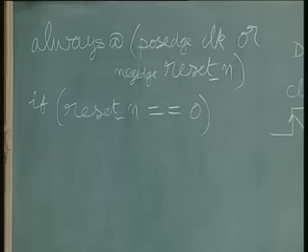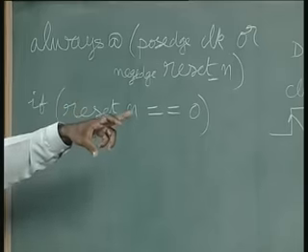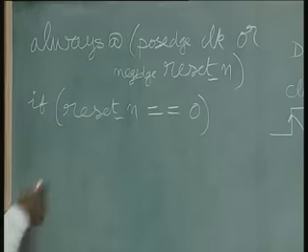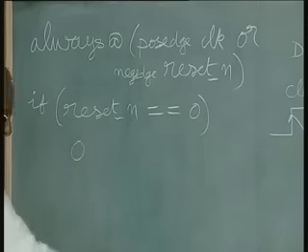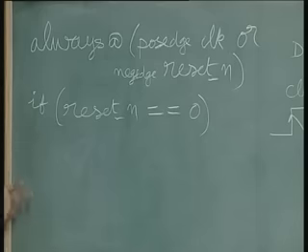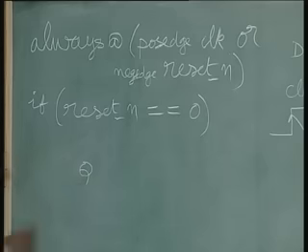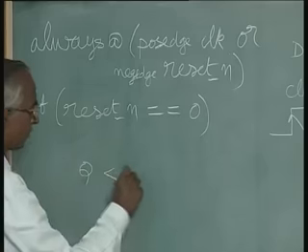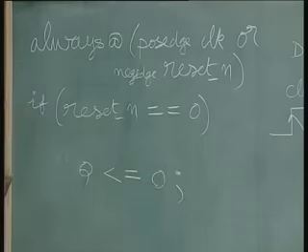For example, now what we want is Q to be reset, that is Q must go to 0, and q underscore n must go to 1. So let us put that statement. In order to do this one, we have only to put q. I will just give a space because we do not know right at this stage whether we need a begin or end. So I will just put that here in case we need it. So q must be equal to 0. Here one statement is complete, therefore a semicolon as in C.